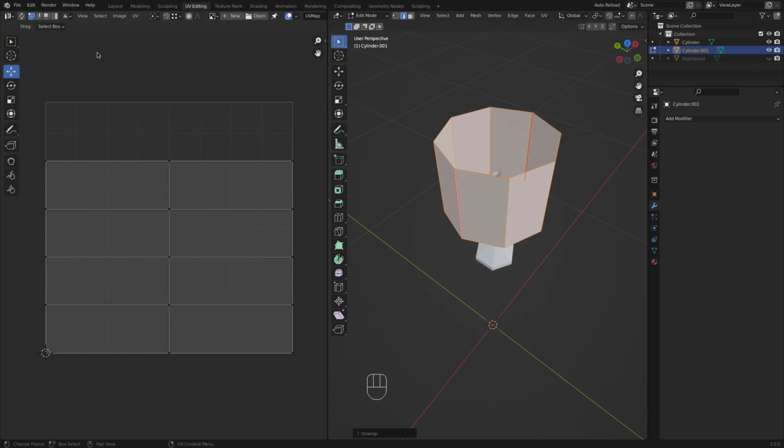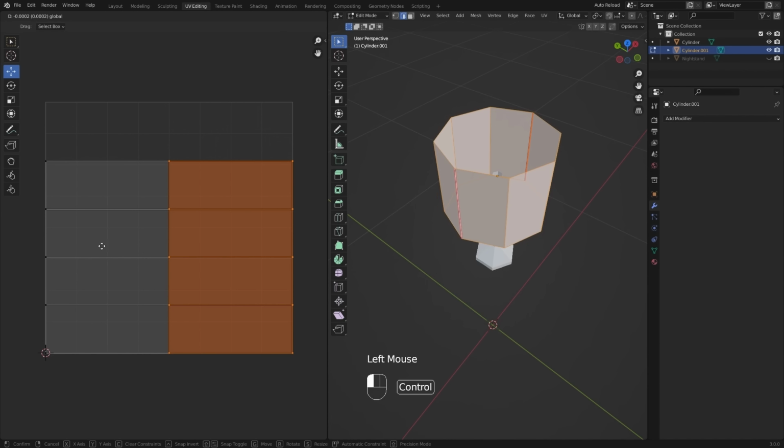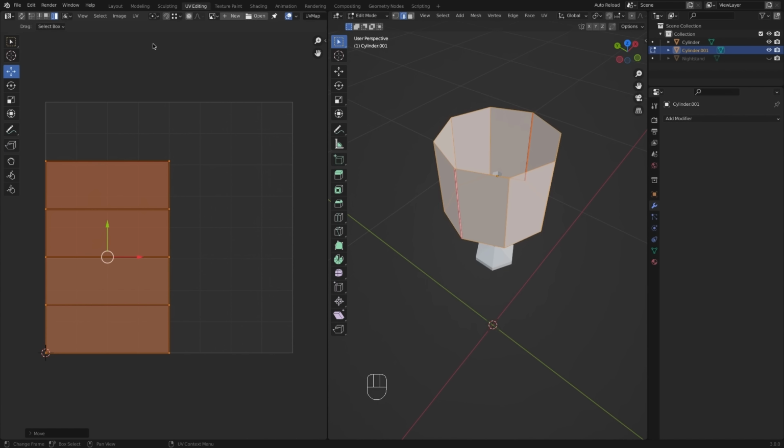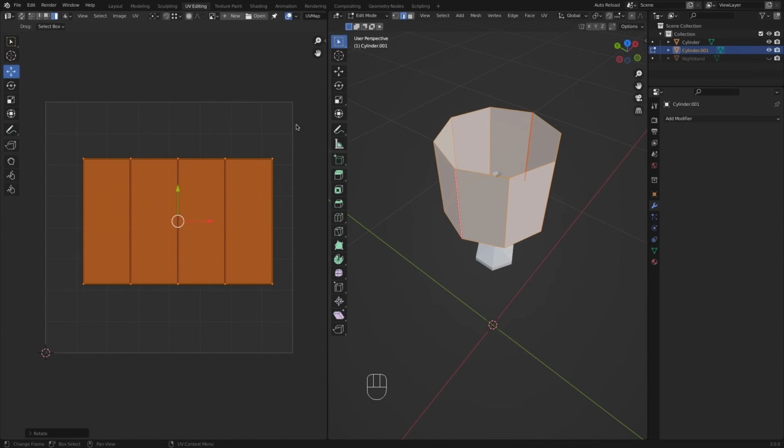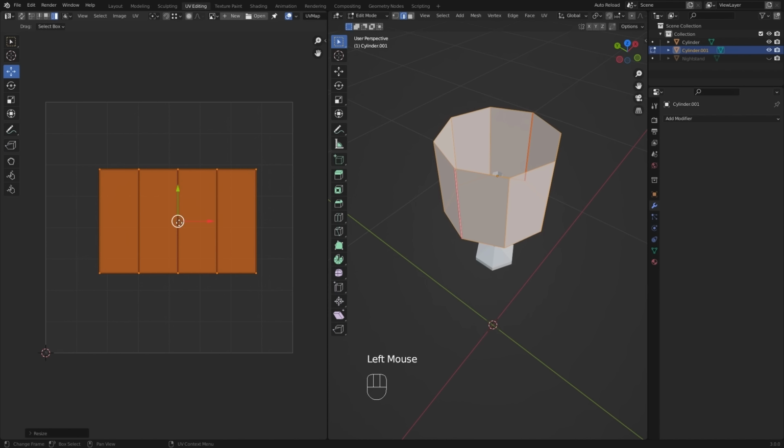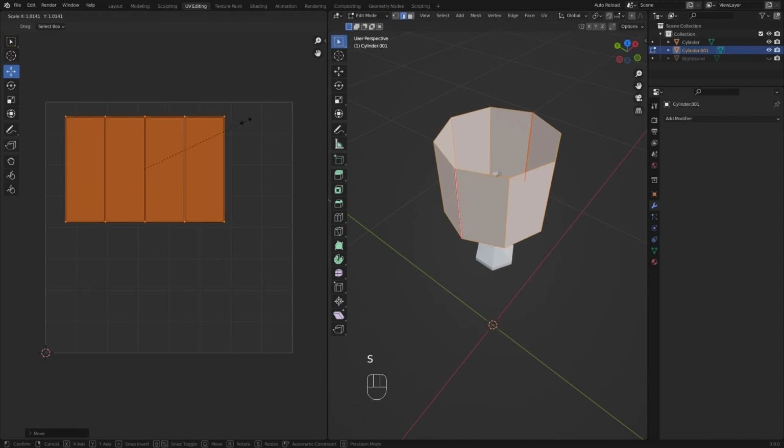In the left window, first change selection mode to island, then just left click on the one part and move it exactly above the other while holding Ctrl. If you remember, we have vertex option selected in Snap to do such tricks. OK, select all of this, hold Ctrl and rotate 90 degrees counterclockwise. Then scale a little and place it, leaving some free space around.